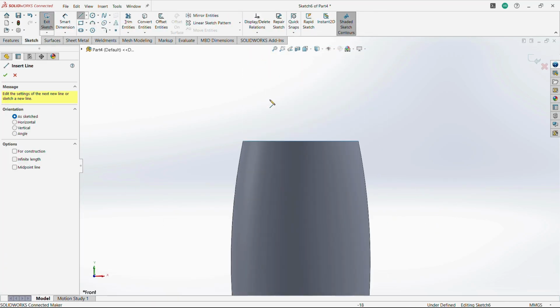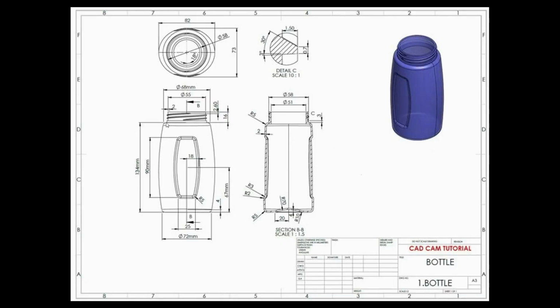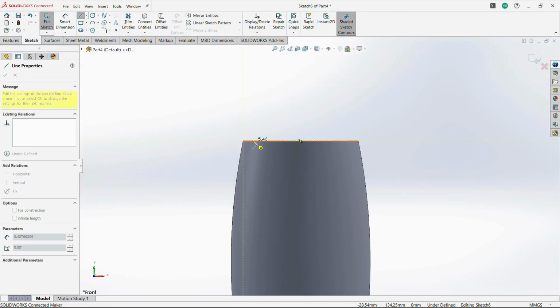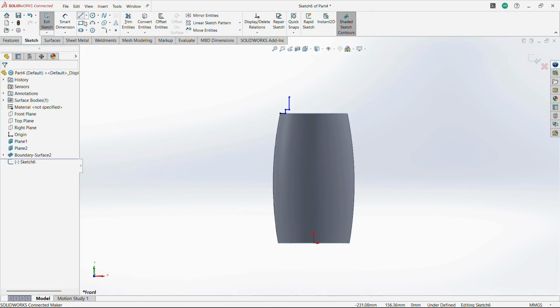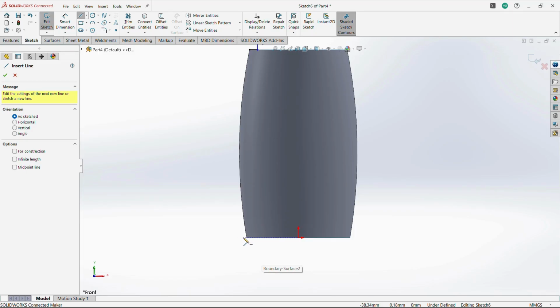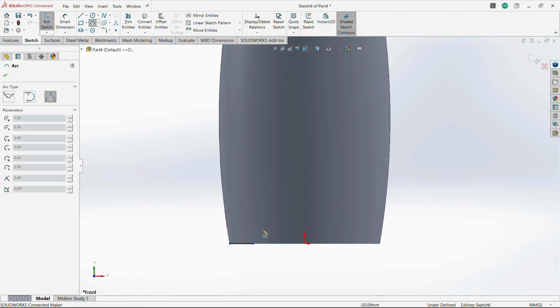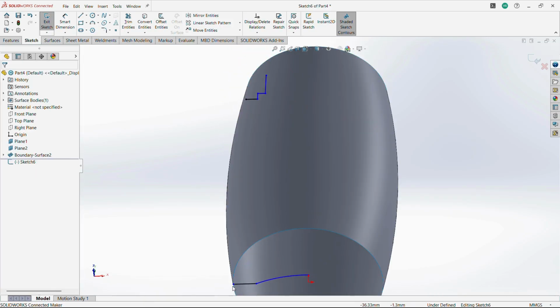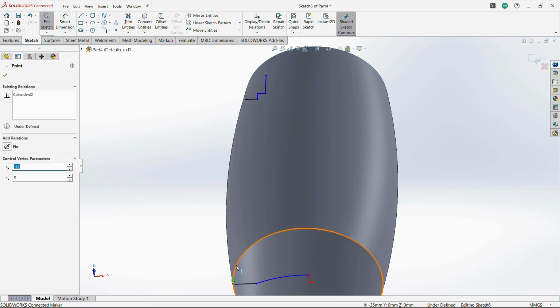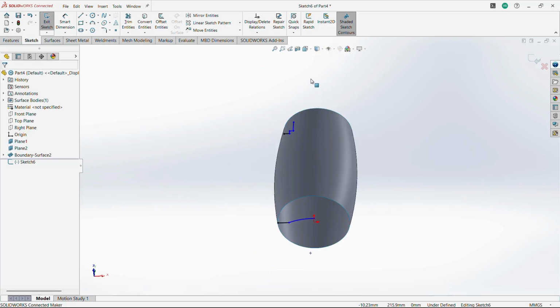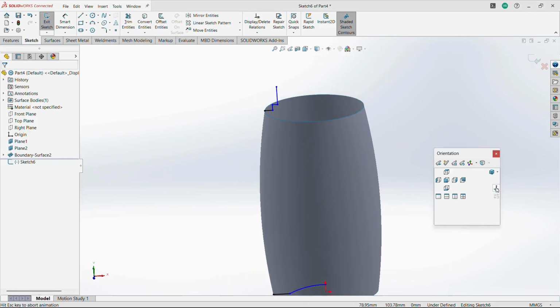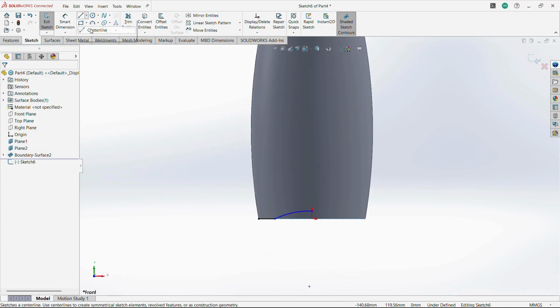Now what I'm going to do is select a front plane and create a sketch, drawing a stepped profile for initiating the thread sections, also the bottom of this closed portion. First draw the stepped profiles, one by one, a complete horizontal profile. Then draw the bottom one. Draw a horizontal line up to this particular portion. Then use an arc profile to draw an arc by closing these opposite points. What we are going to do now is choose this point as well as the circular edges, and make it using a pierce constraint. Afterwards, we fix it using dimensions.